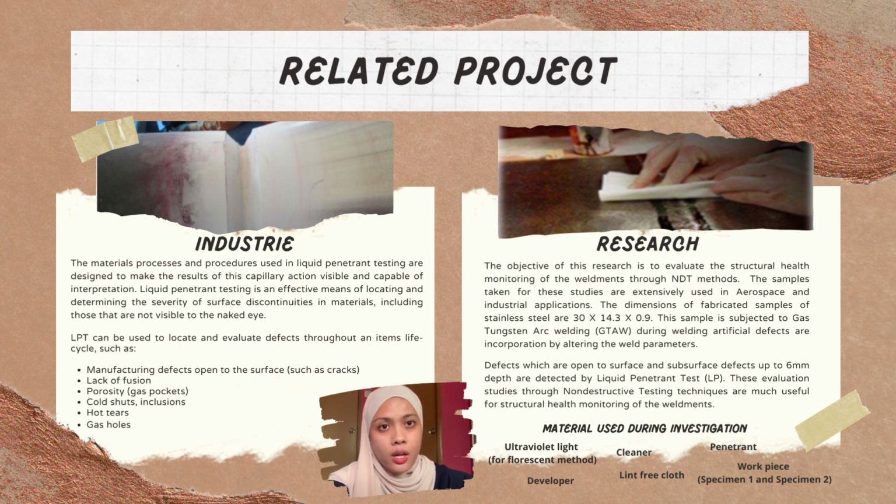Target customers: LPT can be used to locate and evaluate defects throughout an item's life cycle, such as manufacturing defects open to the surface, such as cracks, lack of fusion, porosity, gas pockets, cold shuts, inclusions, hot tears, and gas holes. LPT can also detect in-service discontinuities such as fatigue cracks, HIC, SOHIC, SCC. Early identification of in-service discontinuities means that outages can be planned and executed properly rather than as an emergency. This testing method is used in a variety of industries such as aerospace and food processing.